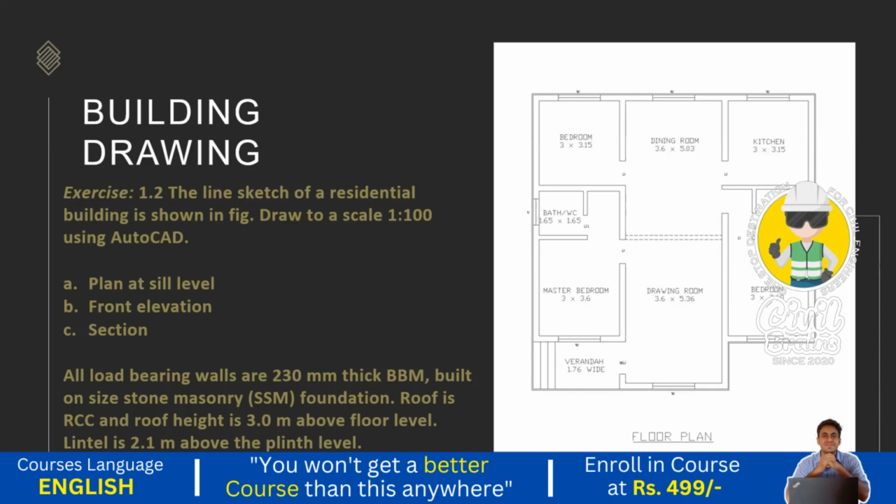Once you draw the doors and windows and ventilators, the next step is we need to draw the plinth line, we need to draw the slab line where the slab will come, or slab projection, we need to draw the chhajja projection, and we need to do the dimensions. Okay, so this is the procedure. Clear? So I just go to the AutoCAD side.